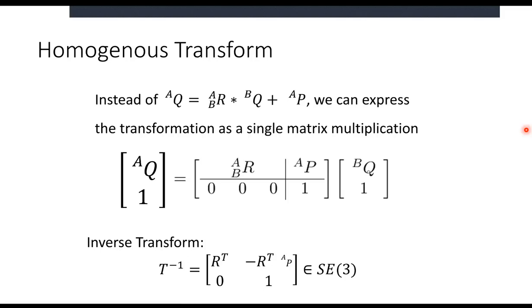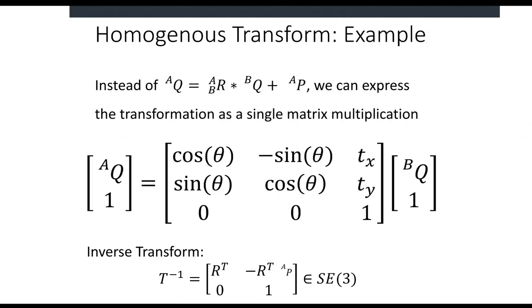And this is, again, something that you will be implementing, you will be using multiple times throughout this class. So let's take the two-dimensional case, right? Because that's going to be the one that we deal with in our epoch, because we only have to care about X, Y, and then theta, which is the robot's rotation. So here, we're going to have the same concept of rotation and translation, and we're going to have it in homogeneous transform notation. So here's our rotation matrix.